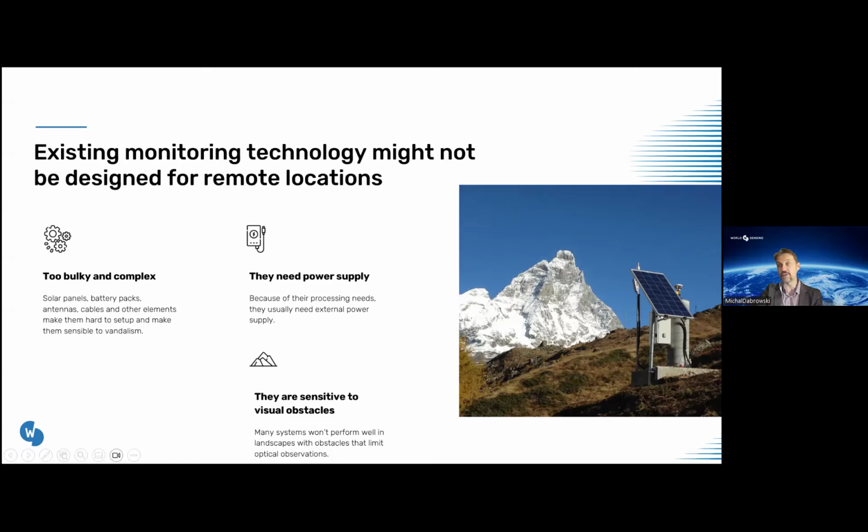It continuously measures the position, and if there is any movement of the ground over here, or over the asset, the role of GNSS is to capture this movement, measure it, and compare it with the allowed thresholds or limits of movement. By this comparison it informs or warns us if there is unsafe movement, horizontal, which means flat movement on the X or Y axis, or vertical, which is basically settlement.